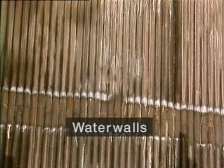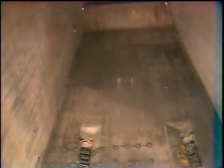The walls of vertical metal tubes that line the inside of the boiler are connected to the steam drum. These tubes are frequently referred to as water walls because they're filled with water. The steam that's used to drive the turbine is produced in the water walls. The water walls surround an open area in the boiler that's called the furnace. This is where combustion occurs. That is, where the fuel is burned.